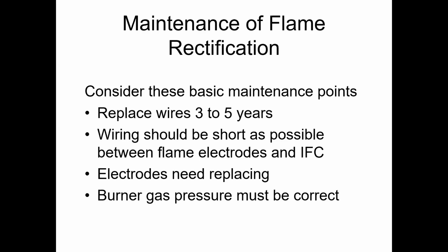The main thing I would do as far as wiring is concerned is test with resistance. If you test your wiring with resistance, you're going to be able to tell whether or not it's working well. Good wire should have close to zero resistance. Bad wire will have higher and higher levels of resistance. We should have a very, very low level of ohms.